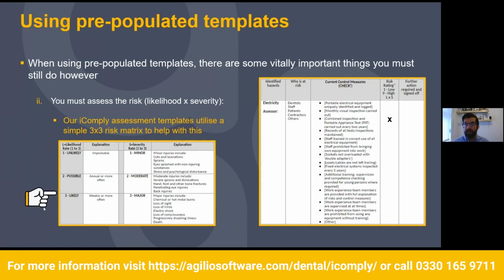So the likelihood, if that's missing, would increase. And depending on the last time it was done, if you've never ever done an electrical installation condition report, I would be putting the likelihood as a 3. It's likely that someone is going to get injured when they plug something into the mains, because you have no verification of the state of repair of it or whether or not it poses a risk. So this is all determined around the control measures you have.